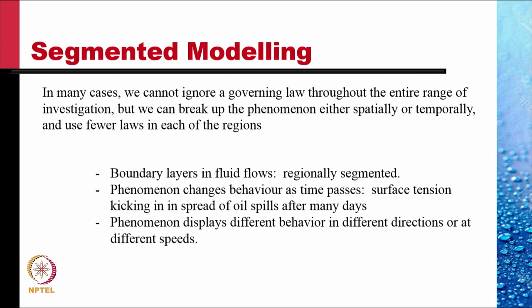One region near the wall where different laws are applied, viscous forces are important, and a region away from the wall, which is called the outer flow, where the viscous forces can be neglected.